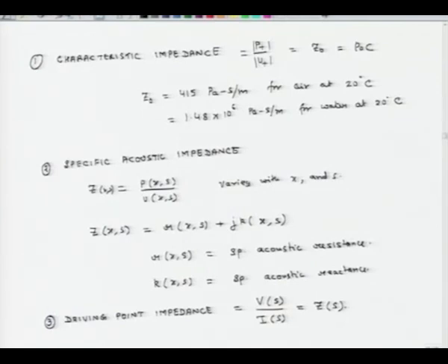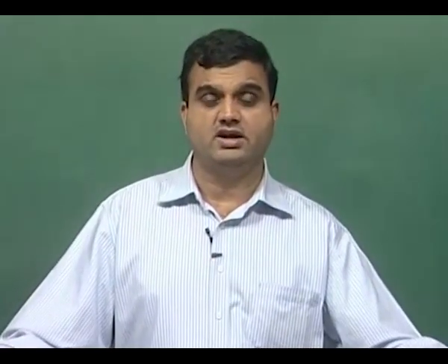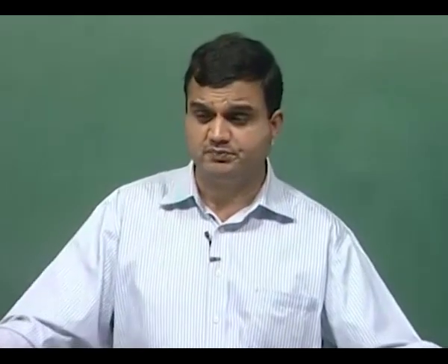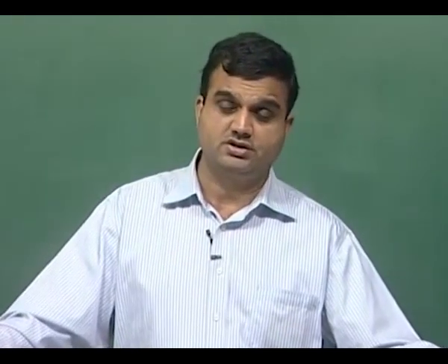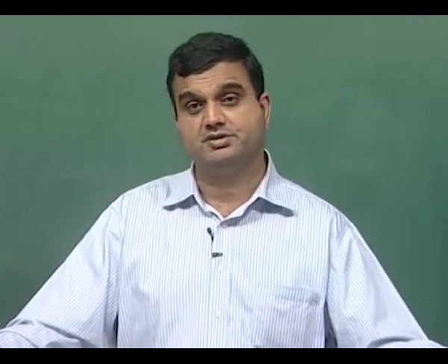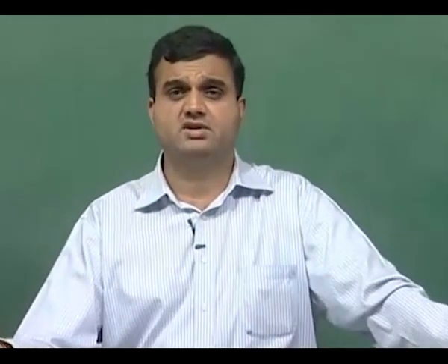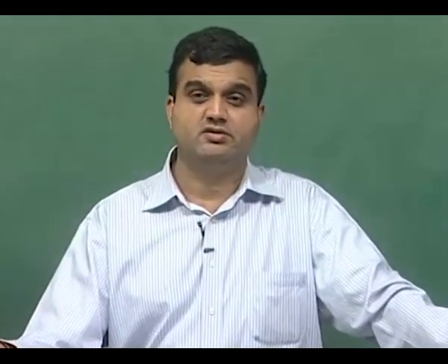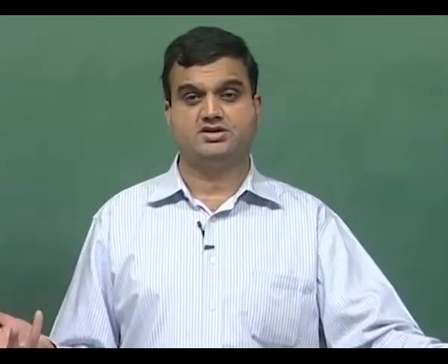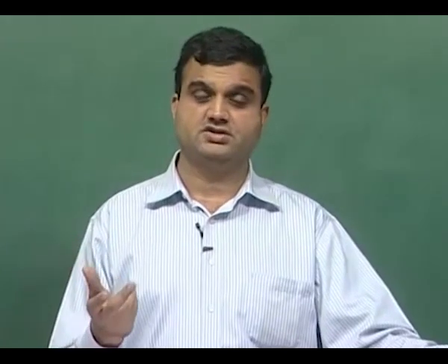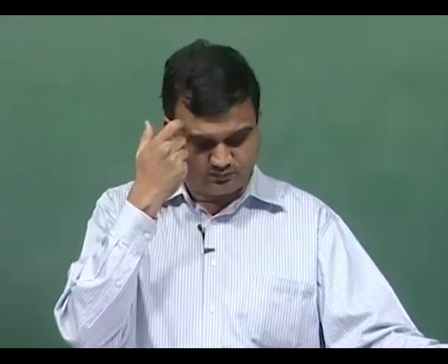So, what we have covered today is a continuation of 1D wave propagation of sound. We have understood that its solution could be represented in very general form as f1 of t minus x over c plus f2 of t plus x over c, and we have understood the physical significance of f1 and f2, and then after that we have talked about waveguides and transmission line equations.